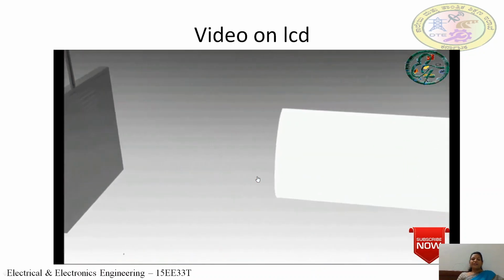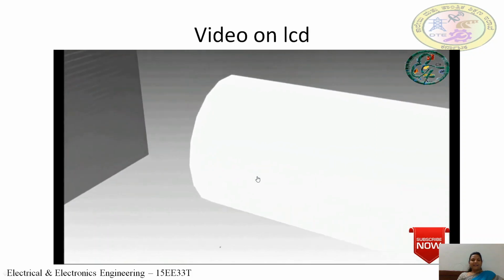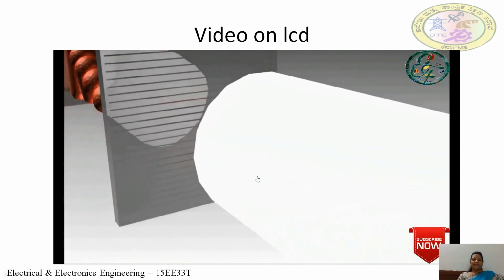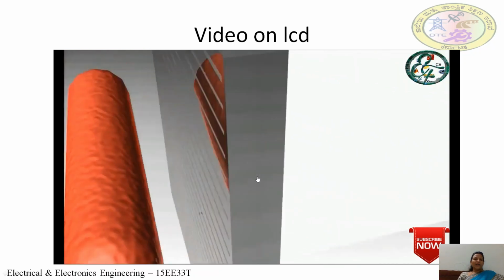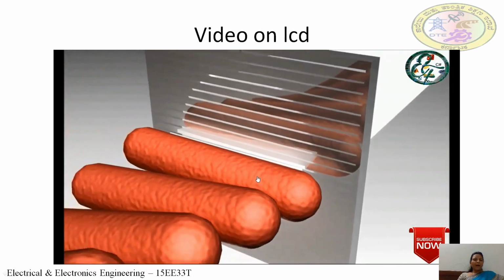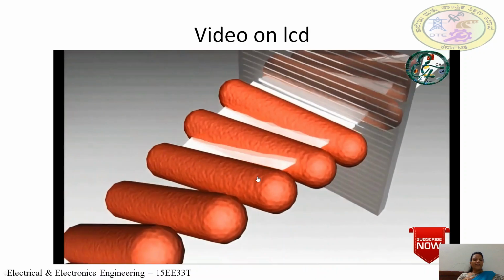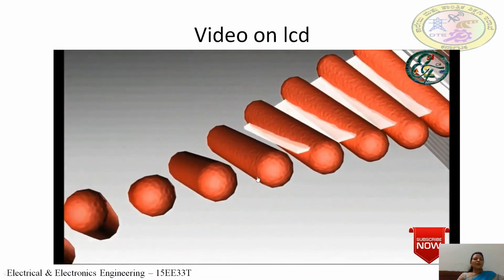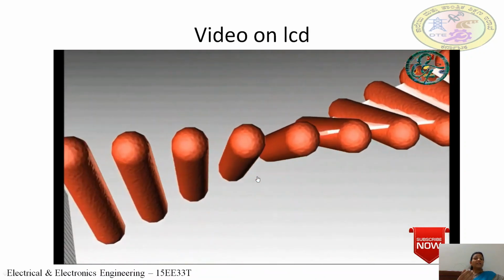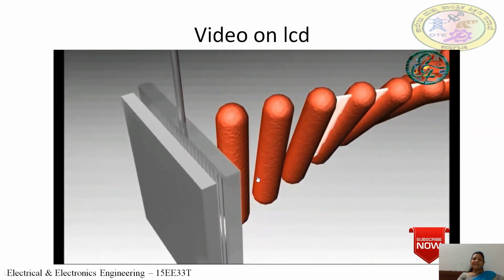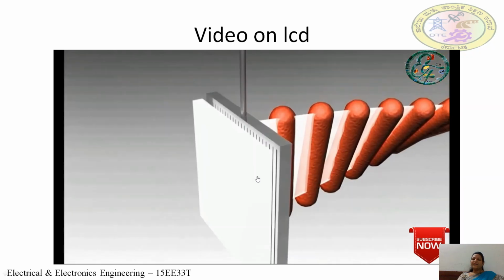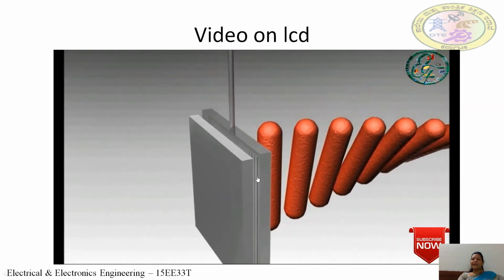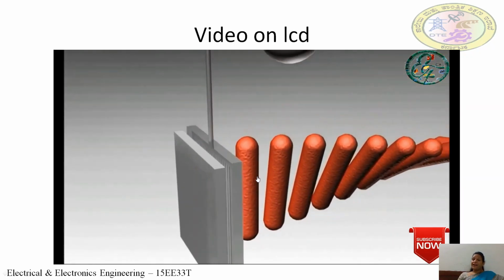Now when you introduce a backlight, let us see what happens. So you are introducing a backlight, a source of light. So this light, as it passes through the liquid crystal, also gets twisted according to the alignment of the molecules and hence reaches the other end, which is the vertical polarizer, and easily passes through the display and the display is brighter.